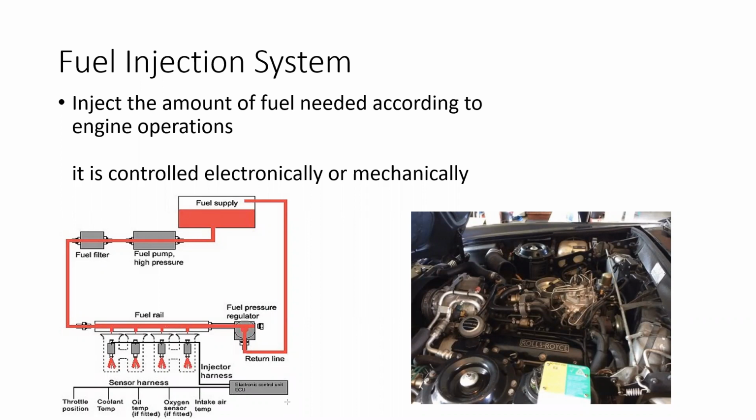So basically it considers the input from the various parameters of the engine, and based on that it provides fuel into the fuel injection system. Fuel will be injected into the cylinder at the correct times and correct amount by controlling each injector, right? These are not the only sensors necessary. There are more sensors than that, especially crank and camshaft sensors, which are necessary to find the TDC positions to deliver fuel exactly.